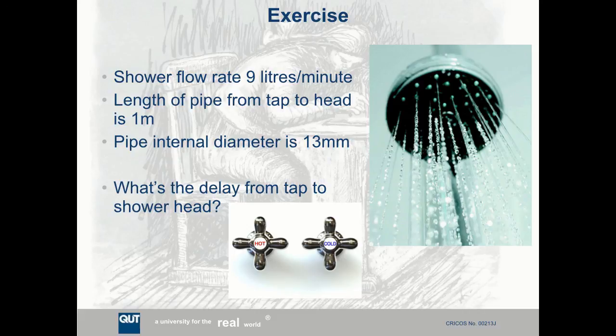Here's a shower. Water's flowing out, 9 litres a minute, the Australian standard. And say you've got 1 metre of pipe between the tap and the shower head, and the pipe's 13 millimetres in diameter. What's the delay between when I turn the tap and when I notice the change in temperature of the water? There's an exercise. So pencil and paper time. It might surprise you. It's not instantaneous.